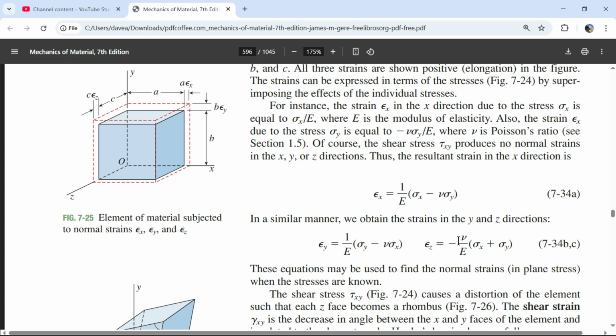I was just like, how do you do it in the z direction? Well, we don't have any tension. And I still like to refer to this as a force, but we don't have any tension or compression in the z, so therefore we don't have any normal compressive or tensile stresses in the z direction that are causing that big change in length in the z.